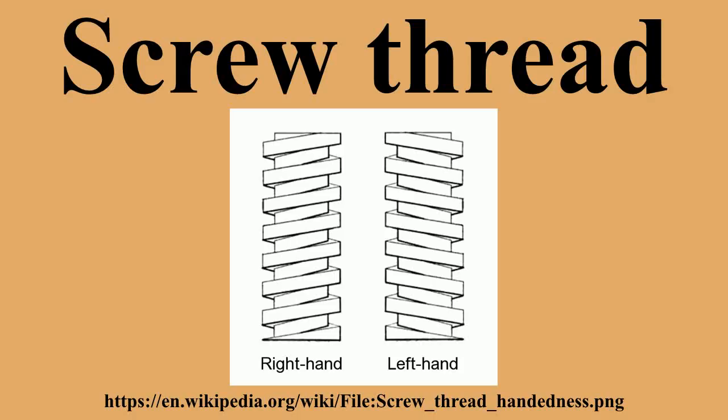A dedicated type of micrometer, called a thread mic or pitch mic, which has a V-anvil and a conical spindle tip, contacts the thread flanks for a direct reading. A general-purpose micrometer is used over a set of 3 wires that rest on the thread flanks, and a known constant is subtracted from the reading. This method is called the 3-wire method. Sometimes, grease is used to hold the wires in place, helping the user to juggle the part, mic, and wires into position. An optical comparator may also be used to determine PD graphically.